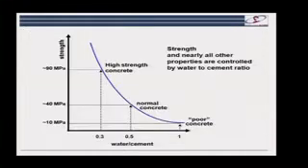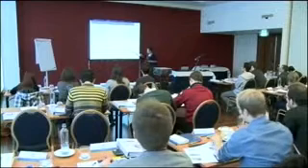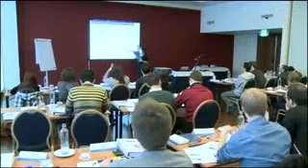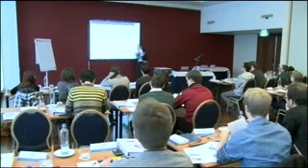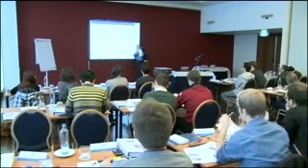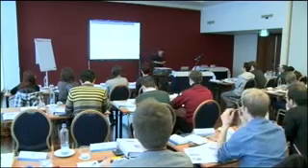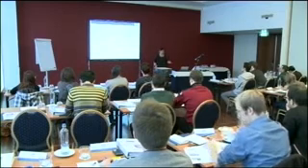And here, again, very diagrammatically, is that information shown in terms of mechanical performance, in terms of strength, that as the water-cement ratio goes up, we come to concrete of lower and lower strength. 10 megapascals would be quite enough, say, for example, for filling in a hole in the road. You could drive a car over it, no problem at all. But it maybe wouldn't be very durable because there's a lot of porosity that can then degrade over time.